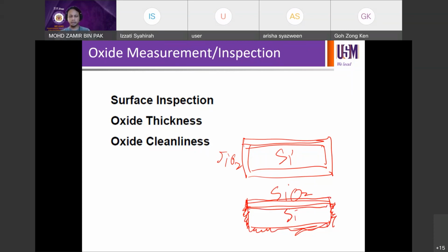Remember, go back to the active region. When we talk about device fabrication, we want to use the top surface. So everything will be built just on the surface, nothing within the bulk. On the other hand, we learned last time in 386 about solar cells, for example. For a solar cell we want to use the bulk, because we want to absorb light everywhere in the silicon, and then the electron-hole pairs will migrate to both sides. Electrons will go into n-type, holes will go into p-type. So you're going to use the whole vertical structure in silicon for a solar cell.